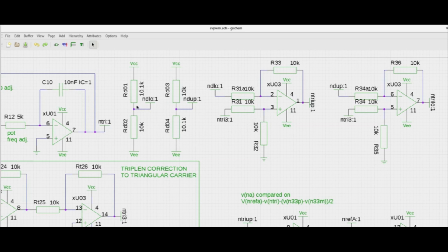and adding. Now let us say there is a resistor divider network here, another resistor divider network here. I am making the attenuator point not 10K, 10K. One is 10.1K in one case. The upper resistor is 10.1K. In this case, the lower resistor is 10.1K. So this will be slightly higher value, and this will be slightly lower value compared to 0, because this is positive and negative. And the higher and the lower values I am going to add to this triangle.